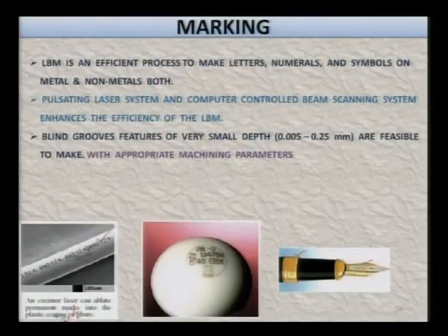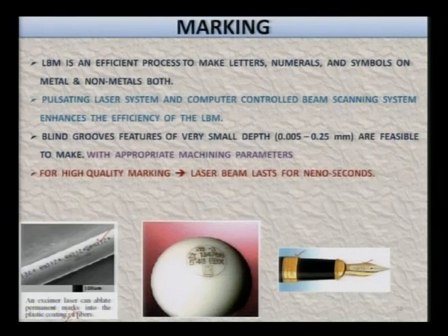Blind groove features of very small depth, 5 micron to 250 micron, are feasible to make with appropriate machining parameters. You have to select the appropriate optimum machining parameters, then only will these blind grooves etc. be possible. Otherwise, making blind grooves is rather a difficult task with the help of a laser beam machining setup.